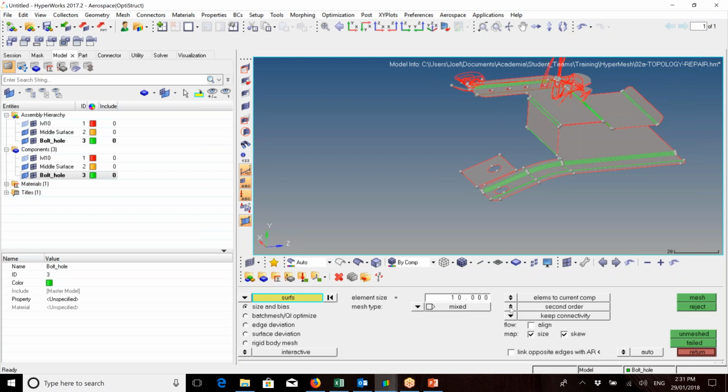So you need to be aware of this, because this is something that can really get you caught out, especially when you're first learning. If you accidentally put in a wrong mesh size, that could be the difference between 20 minutes of work trying to build 2 million elements, and 5 minutes to build only 2,000 elements. So it's always worth double checking before building your elements. I normally always work in first order unless I'm doing something that requires second order.